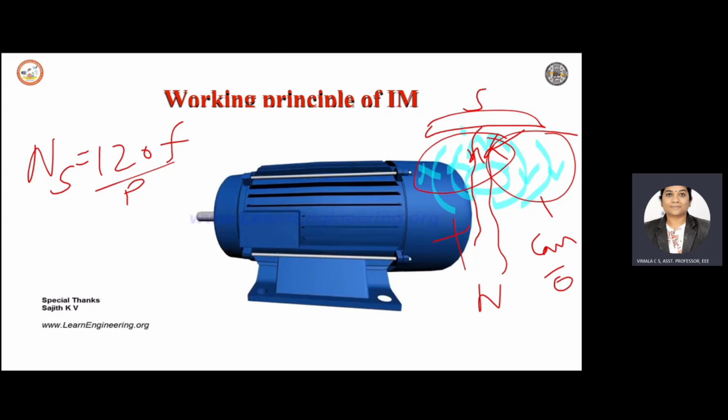When it adds up, there is an interaction of two fluxes, the main flux and the conductor field flux. Where the two fluxes cancel, no EMF is induced in the rotor conductor. Only when the fluxes add is an EMF induced. This is the cause of rotor current: when EMF is induced in the rotor, a rotor current flows in the rotor.